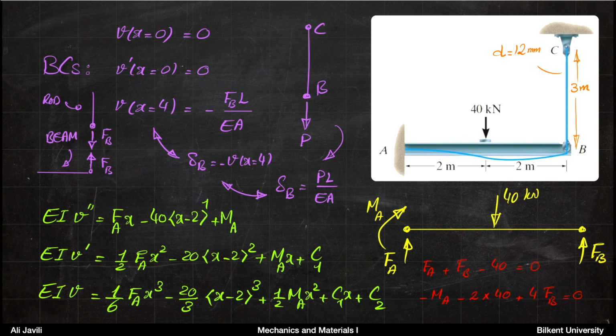So basically what happens here is that the delta at B that you calculate for the rod has a different sign from the deflection at B. In other words, if you assume this is what is happening, the rod is under elongation, so the delta for the rod would be positive, but then this means that the deflection itself is negative because it's downwards.